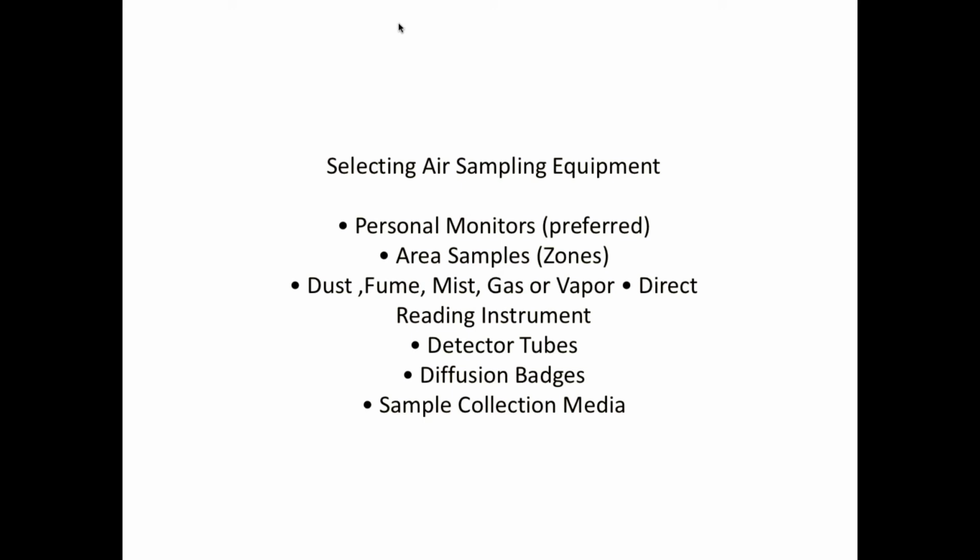Personal monitors are preferred. Number one, OSHA, for their evaluations for safety in the workplace, require that the worker be monitored; they might not be satisfied with area monitoring. For the most part, worker exposures are measured over an average of an 8-hour workday. But in many instances, that may not be practical for a number of reasons. We're going to talk about that when we look at the NIOSH procedure for nuisance dust, for instance.